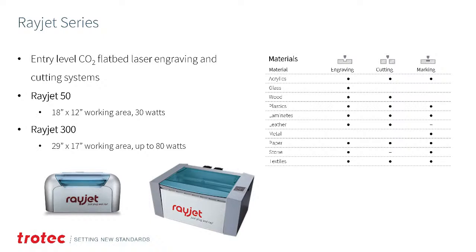We're not going to be able to cut metals, stone, or glass. Basically, a CO2 laser will work mainly and work best with combustible materials. If you want to cut a material and that material is combustible, the laser can cut it. If it's non-combustible, like stone, metal, or glass, the laser may be able to mark it, but it will not be able to cut through it. Materials like metal, even with a fiber laser, you can't cut through, but the Rayjet series machines are going to work with about 80% of all materials out there on the CO2 side.